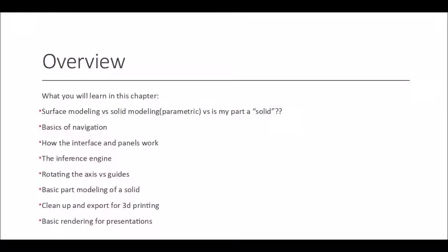So say you have a gear and you want to make the center hole, instead of a 1/2 inch diameter, 0.55. It'll update that and make that hole bigger without changing the dimensions of the other part. So you're basically adjusting certain parameters. That's why it's parametric. It's really advanced.